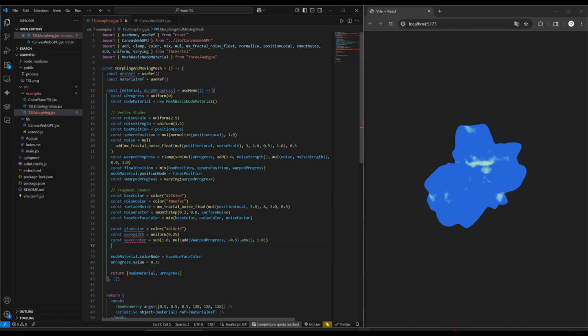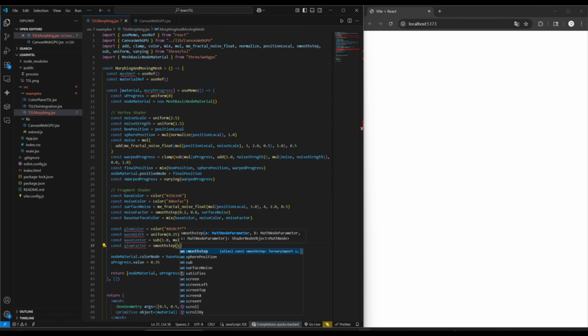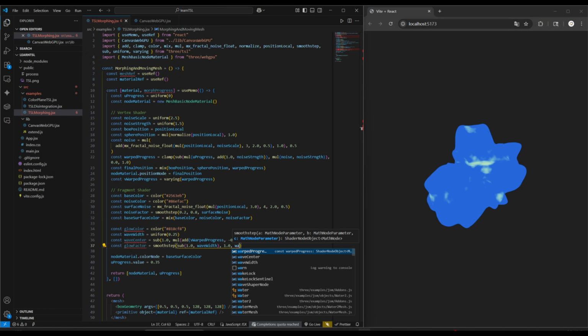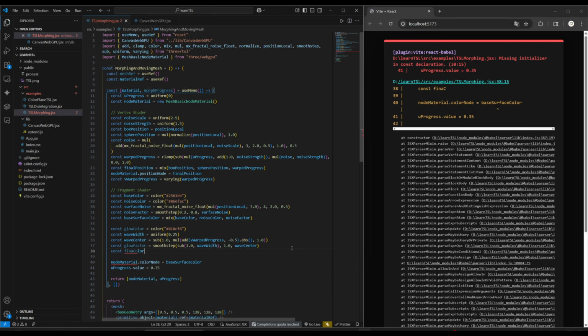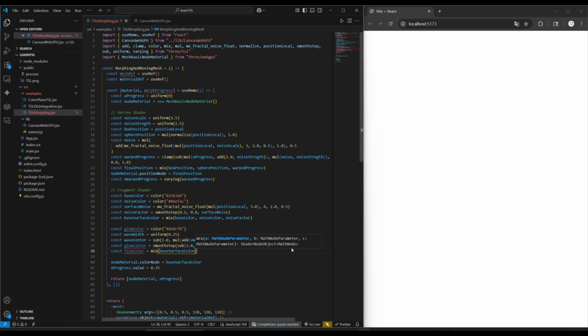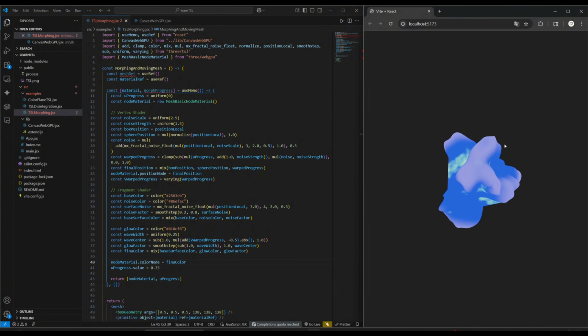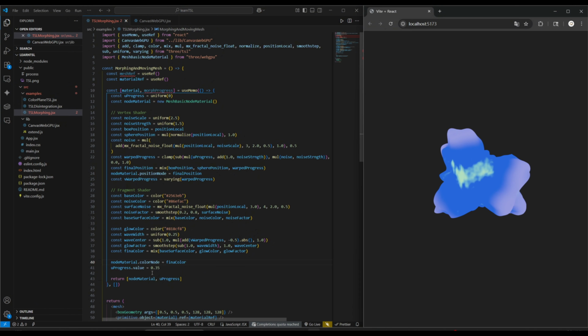Intuition: the closer to the deformation front, the higher the value. Finally, blend the energy wave into the surface color by weight and pass it to color node. A purple energy band now traces the deformation boundary.